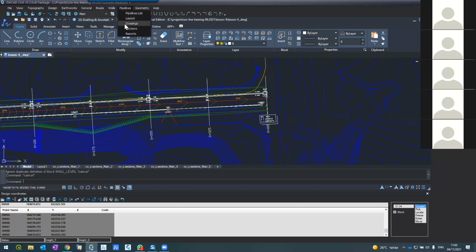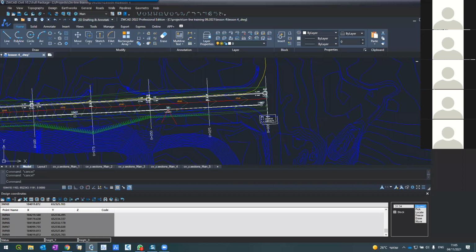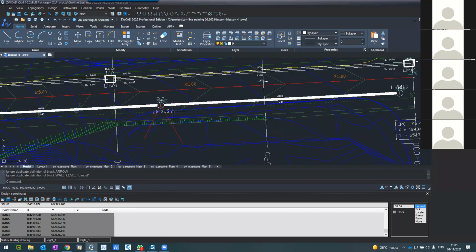It's easier for me, not so important. And I'm saying to myself, this pipe from here to here is, let's say, 400. Oh, it's not entering. From top to down. Okay, 400. And the manhole diameter I will choose later on. Tell the software to choose it by itself. Okay, so this is 400.